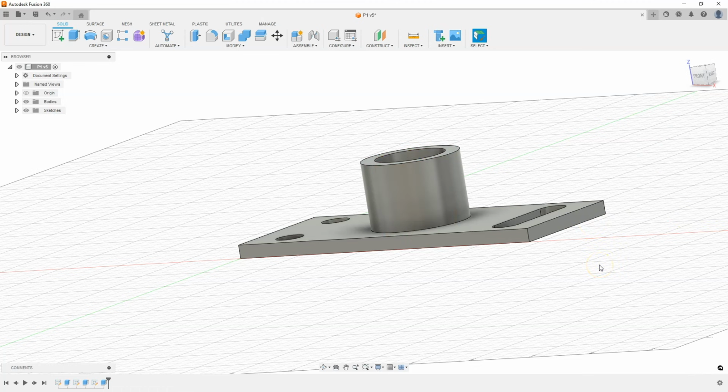And as you know, when designing parts in Fusion 360, we can make changes to previously added operations. Let's assume that we need to change the extrusion of the length of the second segment of this solid, which was created by extruding the circle. And to edit this operation, locate this operation in the operation history.